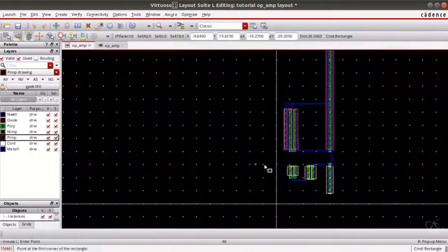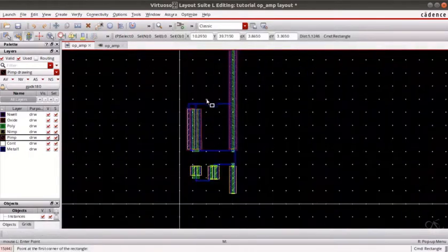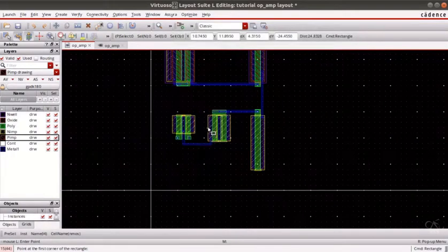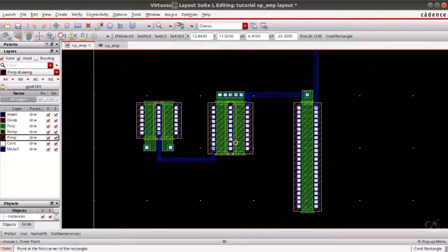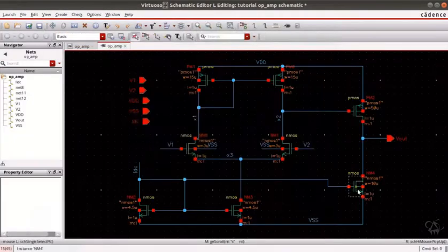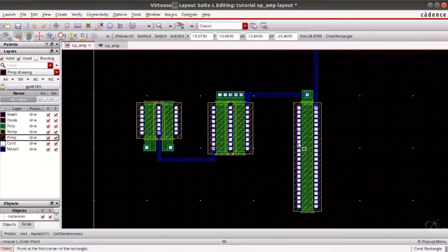Yeah. So now we are left with placing pins and VSS connections. So let us identify the VSS here. So this is VSS. So this is VSS, and also this node X3 VSS IDC. So we have to short this and this, and also give a body connection.